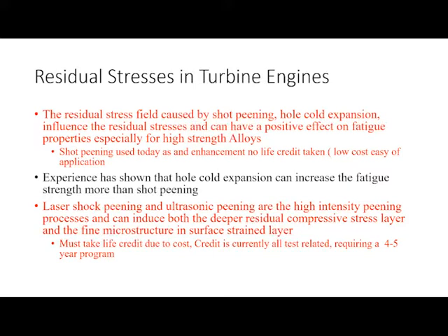The bottom line is they give you this deep compressive residual stress layer in the surface, and that ability for this deep residual stress allows us to take a life credit, but there is a pretty substantial cost associated with it, both production as well as qualification.